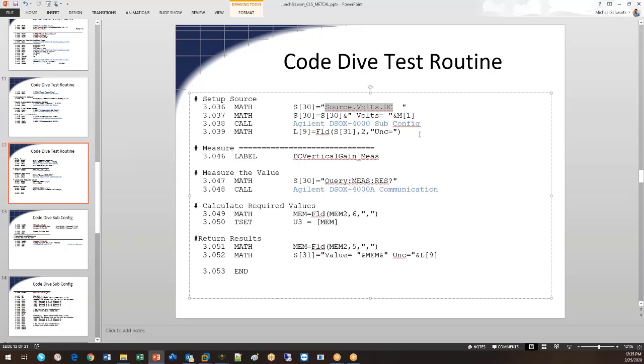So here you can actually replace inside of your configuration file, you could replace it with a driver that's a power supply that's monitored by a voltmeter. And the voltmeter and the power supply are going to continue in a loop until the voltmeter reads 35 volts out of that power supply, and then comes back and returns you the value of it plus the uncertainty. So it allows you to have these multiple ways you can come in and do these things.